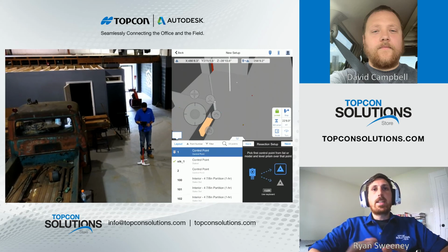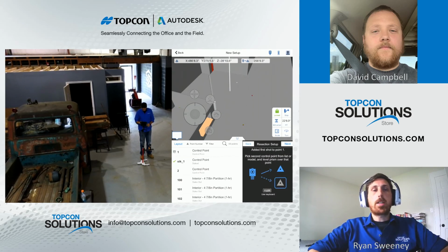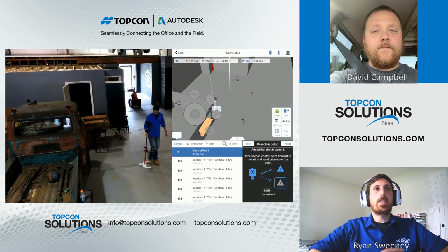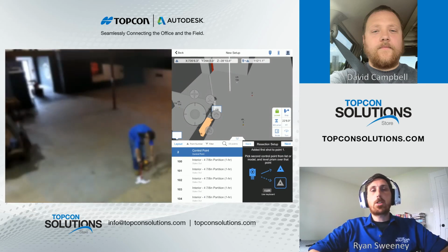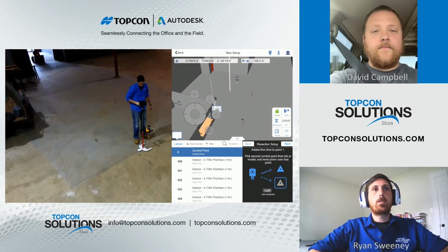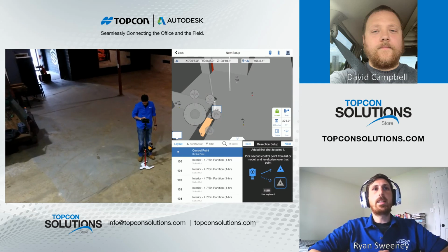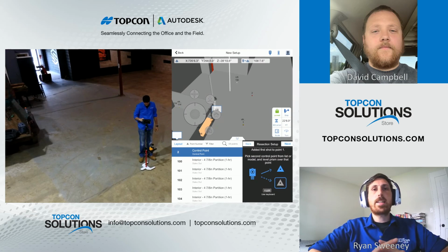Once you're connected, as soon as you get into that first screen where I showed you in the last step of the little target, it's going to automatically ask you all these resection setups and walk you right through all these tutorials, which is nice and easy. So after we took that first shot on point 1, we're going to walk right back on over to point 2, and just like we did in step 1, we're going to select point 2, and then in the right hand corner of the little box, we're going to hit next once we're set up, level, and right on top of point 2.